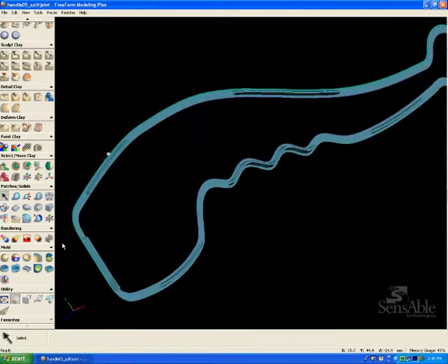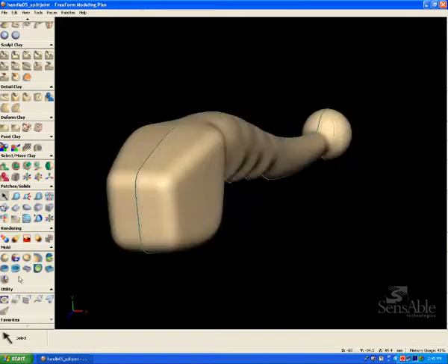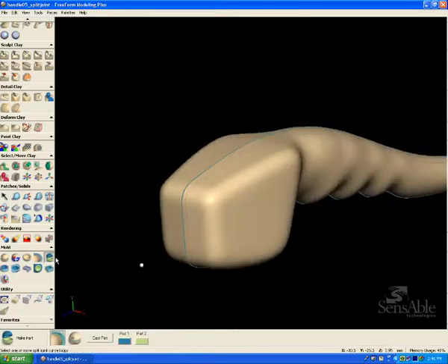Right now I'm just going to open up the next file just for demo purposes. You can see that I did the entire part, just adding some groove joints incrementally around the split joint.